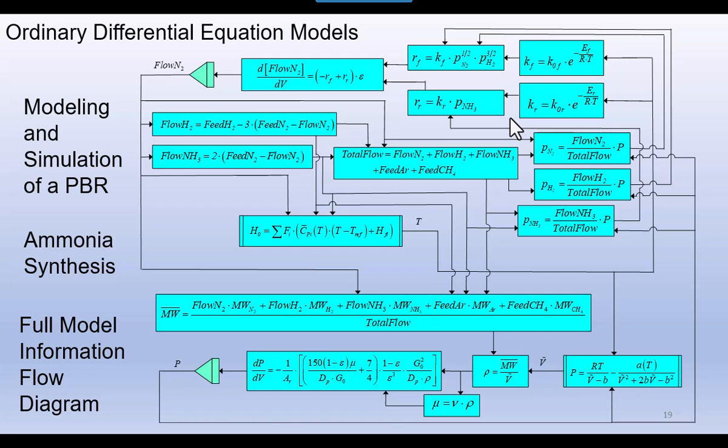So because we're removing the assumption of constant heat capacity, we do not have a differential equation anymore for the temperature. Rather, we have an enthalpy balance where we take advantage of the fact that the total enthalpy does not change going down the reactor. And so we have a relationship here that the enthalpy at any point in the reactor is equal to the initial enthalpy.